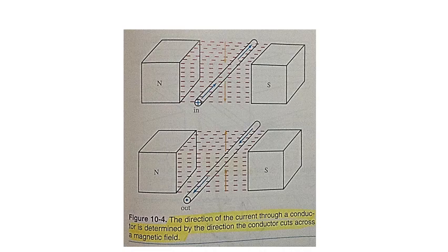This phenomenon is stated in Lenz's Law. The polarity of an induced electromotive force is such that it produces a current whose magnetic field always opposes the change in the existing magnetic field. More simply said, Lenz's Law states that the field induced around the conductor is opposed by the existing field.